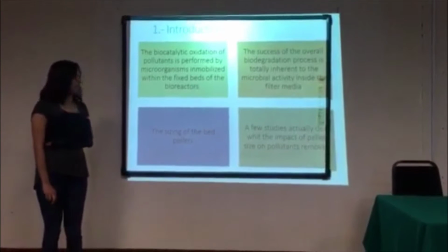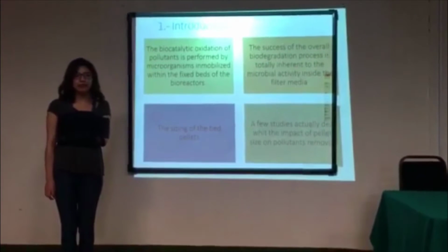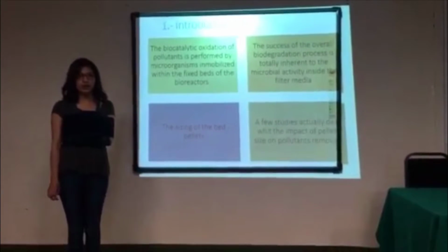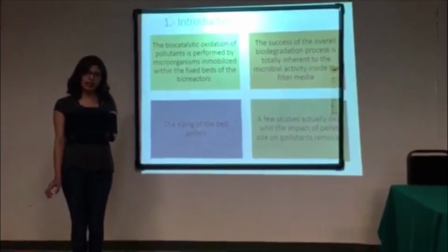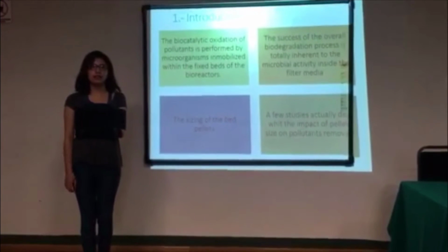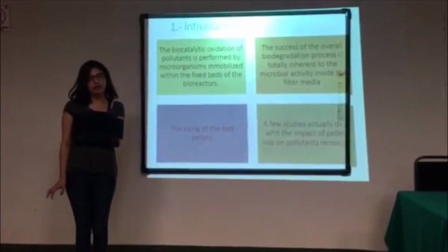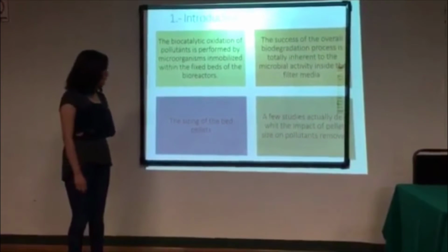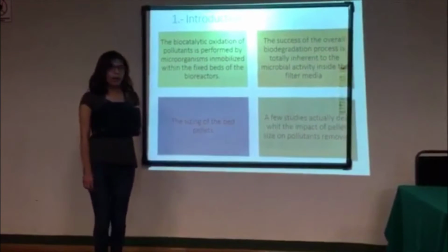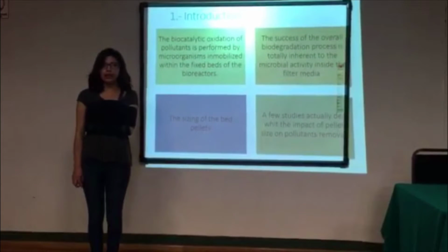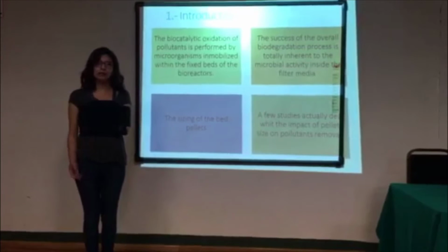About the sizing of the bed pellets, it says that if it's too small, this provides a large specific surface area, but if it's too large, it favors gaseous flows but reduces the number of potential sites for the microbial activity. And few studies actually deal with the impact of the pellet sizes on pollutant removal.